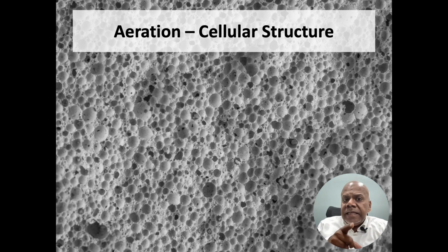You can see that between each two cells there is a separation, a wall of our AAC material, and that makes capillary action difficult to happen, and therefore the water seepage issues are far less with AAC compared to red bricks.